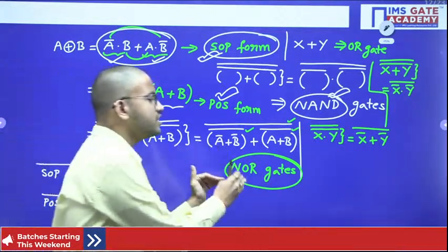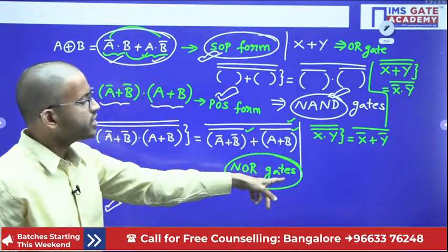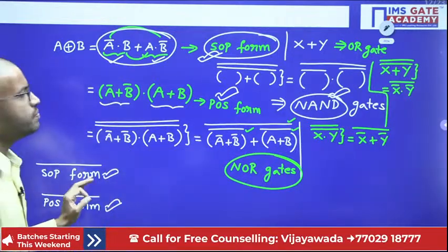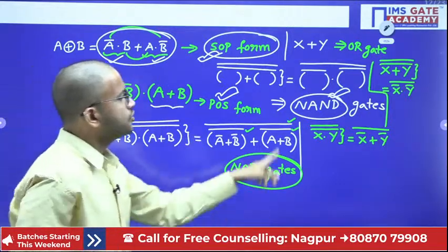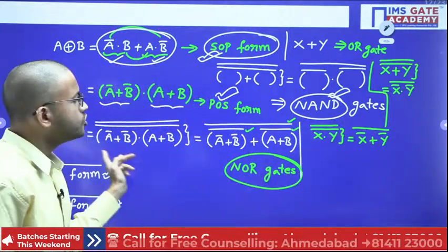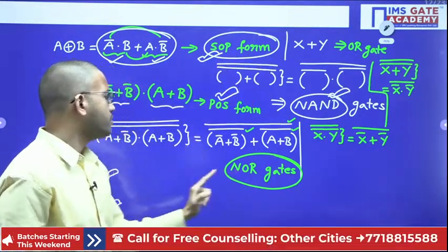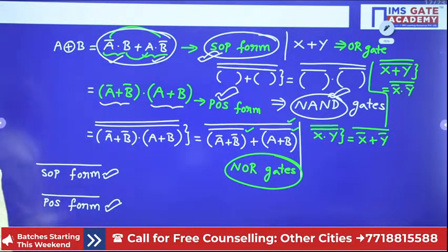So after this circuit, just add one more NOR gate, but that NOR gate should behave as a NOT gate. That's all. Because our requirement is that in the entire circuit diagram you should have either only NAND gates or only NOR gates. That is the reason we are using a NAND-based inverter or NOR-based inverter at the last stage. I hope it is clear for everyone.